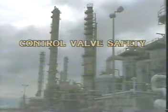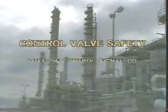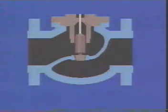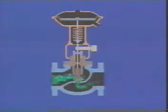You must decide what valve action is needed in case of a loss of control signal or actuating power. Should the valve open? Should the valve shut? Or should the valve remain in its position at the time of the signal loss? Obviously, the action taken depends on the combination of valve style, actuator type, and auxiliary devices.